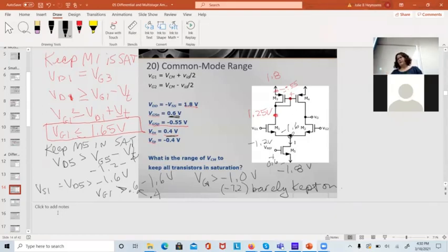You could technically get voltages down to -1.2 out of this, but it would not be very linear, and your circuit wouldn't be behaving properly. And turning down the voltage would be nice because that'd be less power consumption, right? Yeah, you'd have less current and less power consumption, but you'd lose the linearity of the circuit.